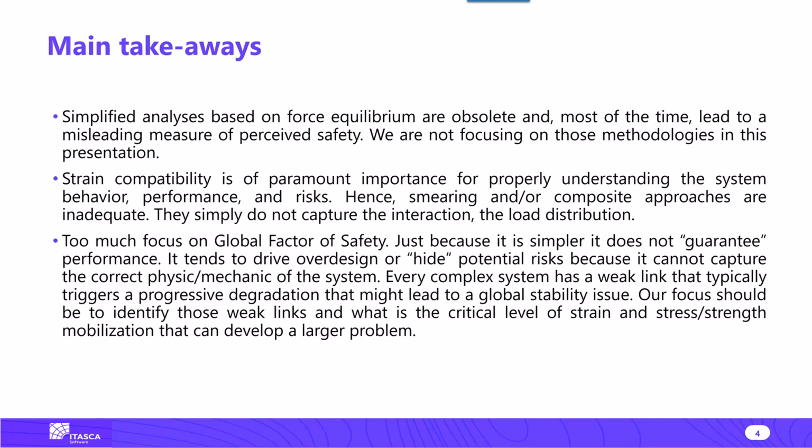I already mentioned that we are not going to focus on simplified analyses that are essentially based on force equilibrium. Personally, I think they are way overused and obsolete for most of these analysis cases. The problem is that there is no strain compatibility, as mentioned in the second point. So you only have a measure in terms of forces, but nothing in terms of strain mobilization and strain compatibility.